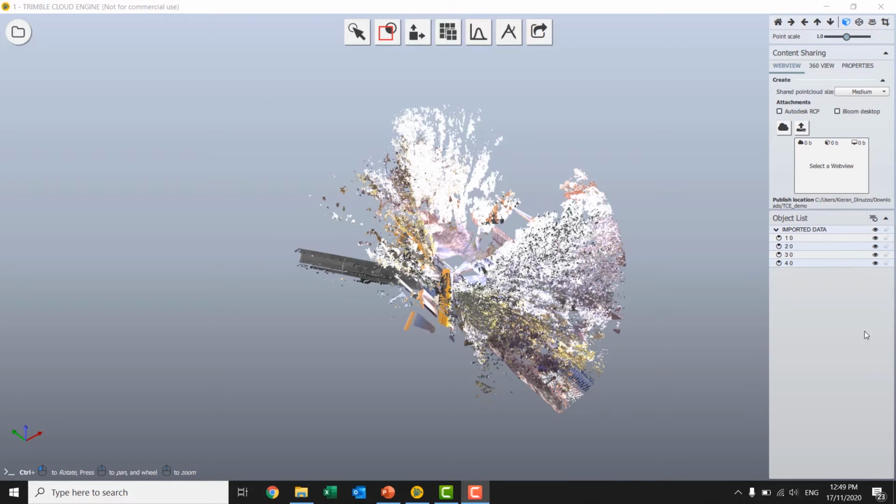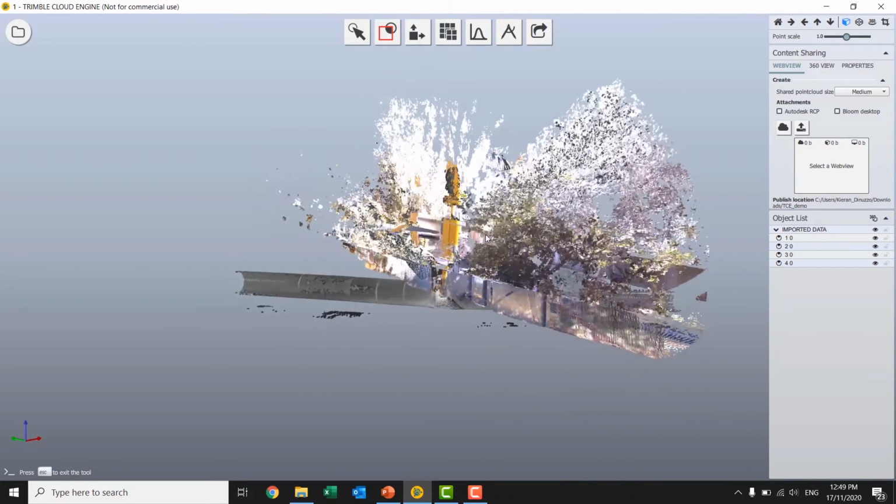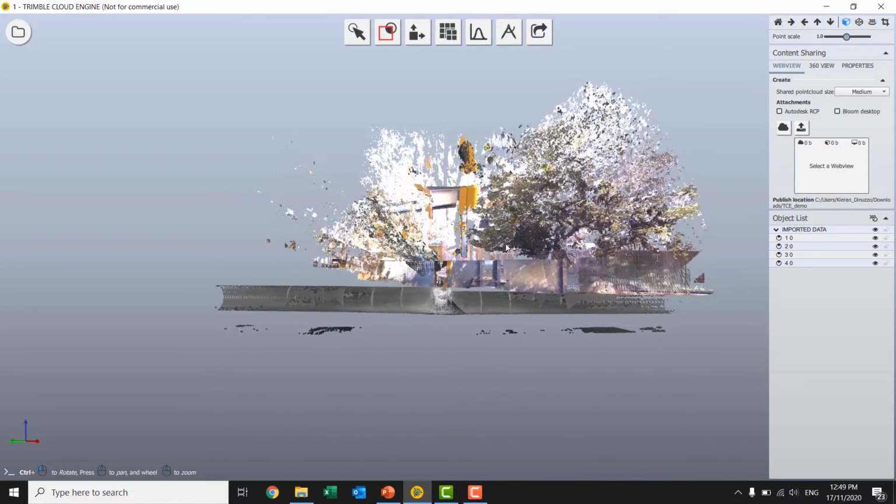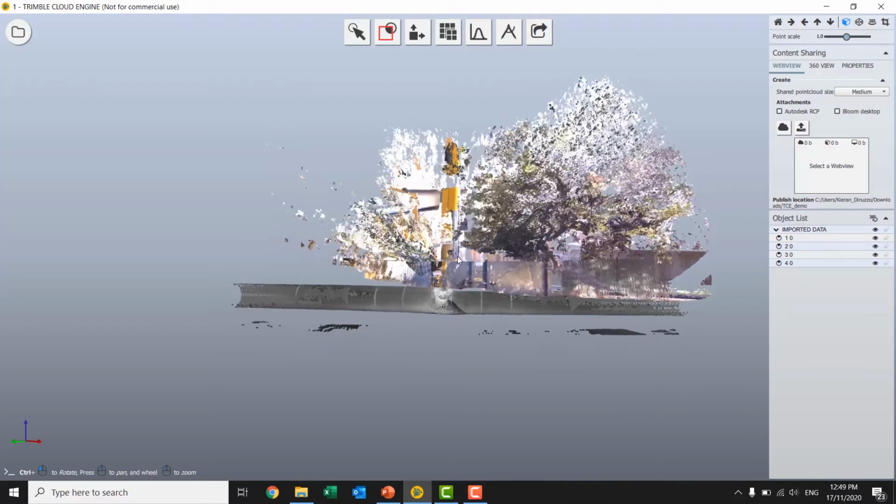That import's finished up now, 2.5 minutes, something like that. Fairly small set of data, just 4 scans here. So that's obviously depending on how much data and what your computer looks like. But in this circumstance, we've got some interesting manhole data. So we took the X7 scanner and started on top of a tripod and then inverted and elevated down.